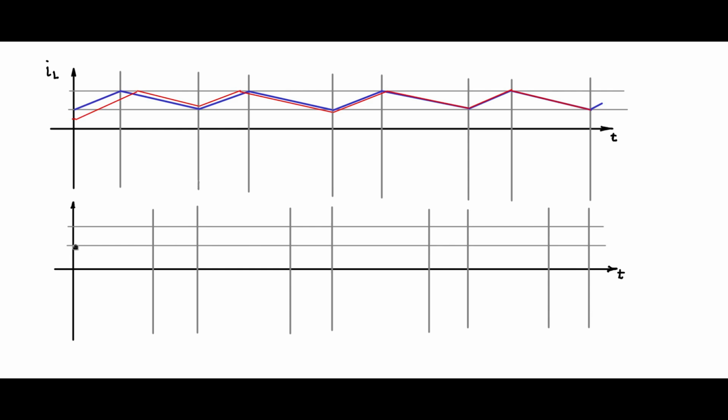And what is the steady state normal expected value of the inductor current? Let me first draw that. So this will be V in minus VB by L. This will be minus VB by L, negative slope, positive slope, negative slope, positive slope, negative slope, so on. So this is the normal expected steady state value of the inductor current under duty cycle greater than 0.5 also. Now here also, like here, we will introduce a disturbance. A disturbance has occurred due to whatever the reason.